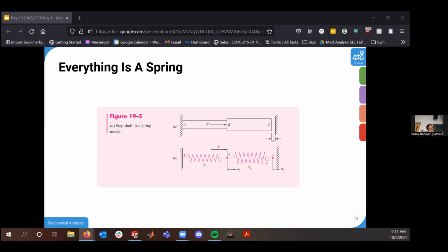Does that rough idea work for everyone, that you can approximate your nodal displacements and relate them to the forces through some stiffness matrix? Yeah? Okay. If you haven't taken ESA, or if you recall back to ESA, we make the same assumptions when we're calculating the natural frequency of an object. We are approximating it as some first order spring.